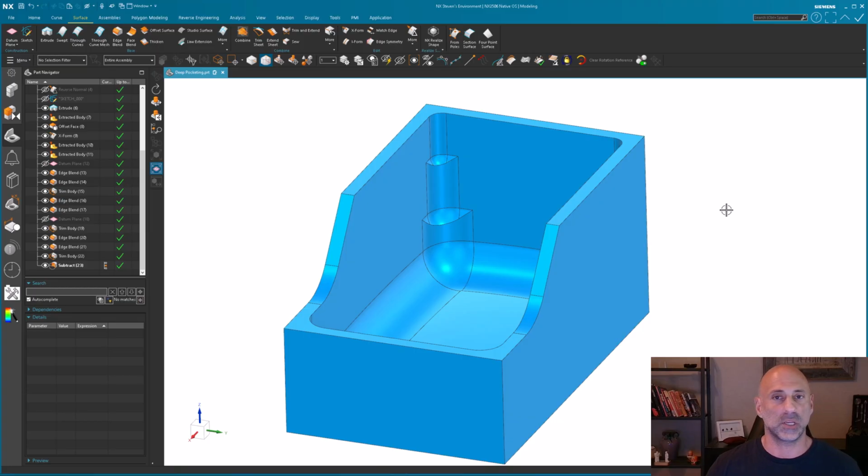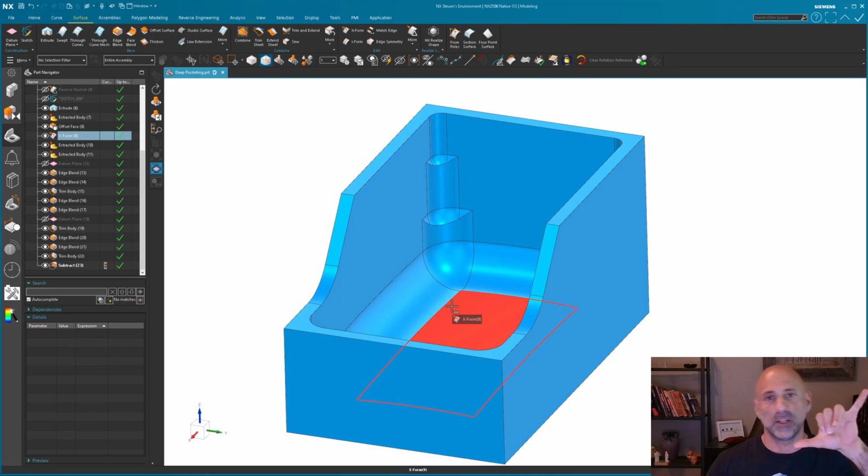It's a good sized part, but you just can't get in there with a skinny ball that's going to reach all the way to the bottom, because you can't have a cutter that's 7, 8, 10 inches long, that's 4, 5, 6, 7 millimeters in diameter, and expect to hold any kind of accuracy at the bottom of a very deep pocket. So how do you do it?